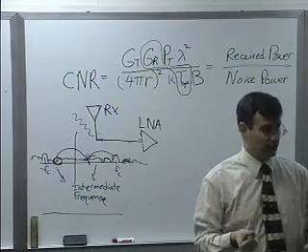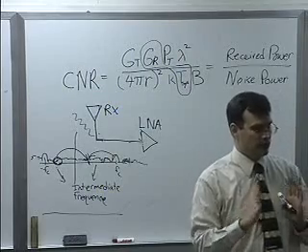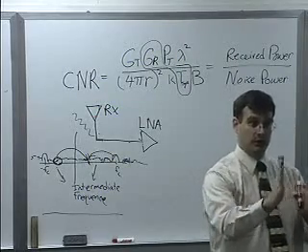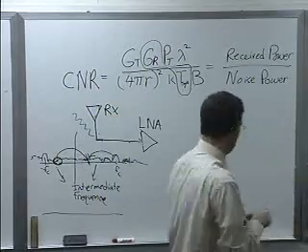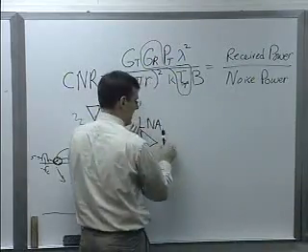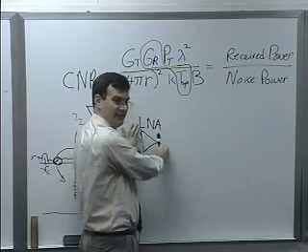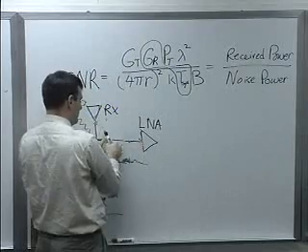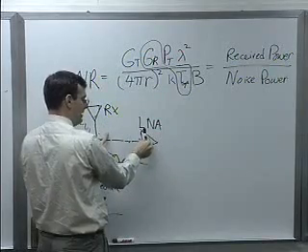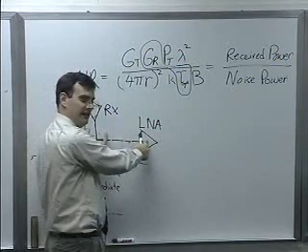If you're really concerned about that, you can put a nice tight filter and notch that area out. But you would generally want to do that a little bit later after your LNA when you've cleaned the signal up already. So the purpose of this one is just to give you enough filtering to keep this device from being nonlinear.